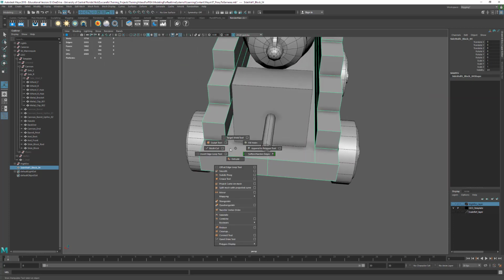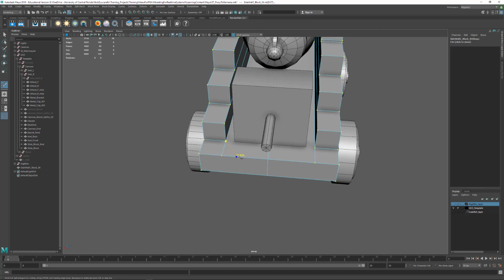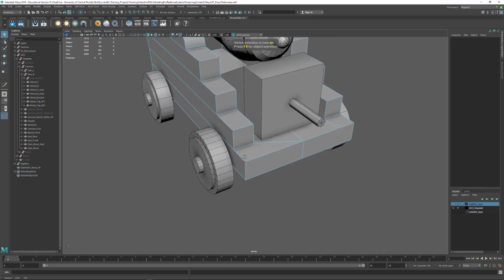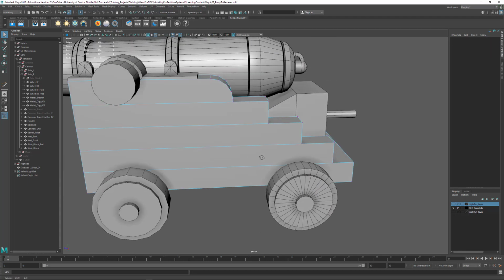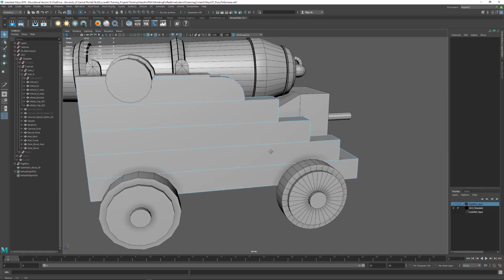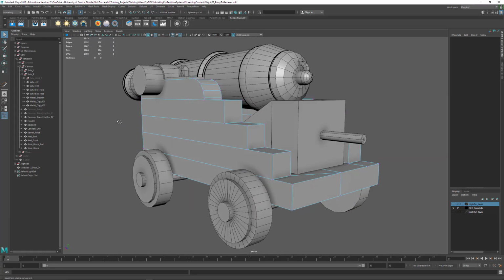So if I do Shift, right click, and multi-cut tool, like if I go from here to, let's say here, I know I don't necessarily need geometry going down the center, but I'm just going to keep it there so we can just keep merging here. Hit F10 to get rid of this edge. Hit F9, select verts, get rid of verts. So that's going to be a pretty normal and standard kind of thing that we would be doing with the geometry. Now we could leave all the splits going in through here.